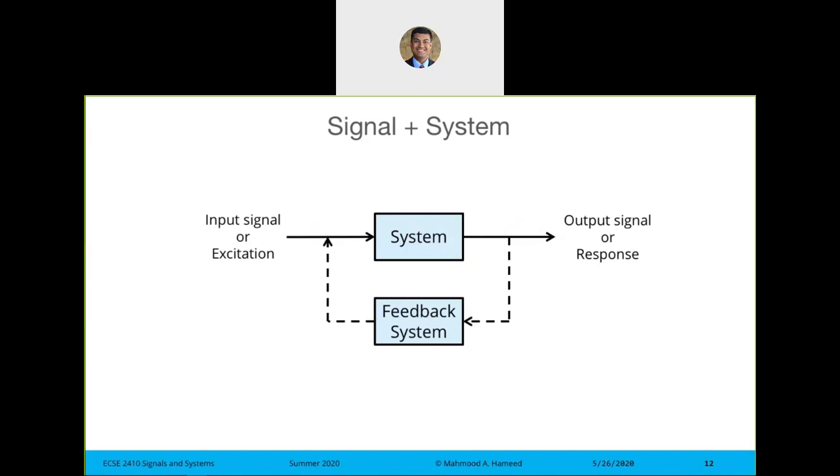Actually, you can think about the feedback in terms of a microphone, right? If you have a computer volume up and your microphone is also on, there will be a feedback loop created because you have a computer volume up and you have your microphone active. And if there is positive feedback, if the gain of your system is greater than 1, then you will have that very uncomfortable sound because of that feedback happening. That's another example of positive feedback where it could lead to some uncomfortable hearing. And then you reduce the gain of your sound system so that it is still a speaker, but a controlled feedback.